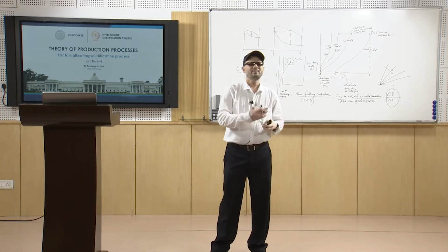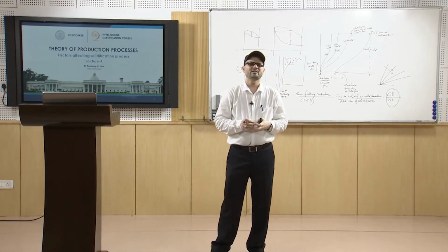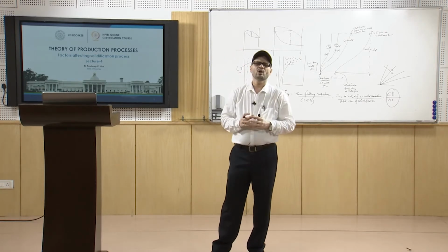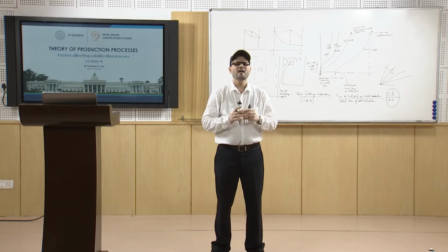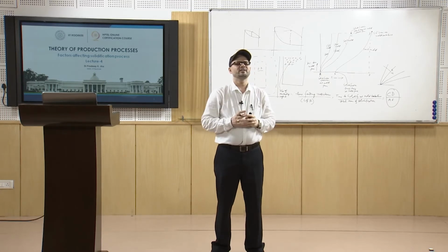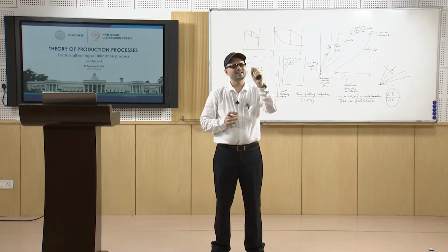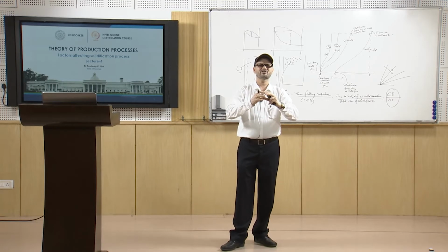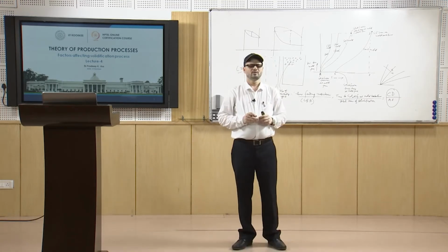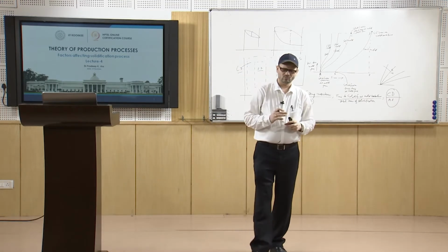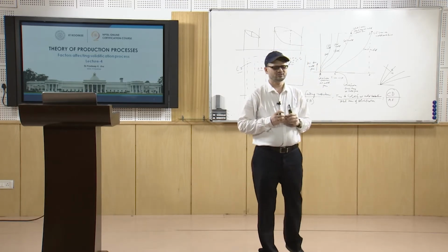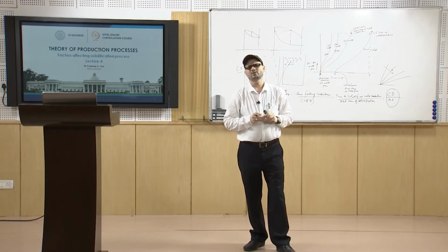So, you have many ferrous materials, a variety of steel, or duplex steel, which basically use these nucleating agents to refine the structure and make the grains refined. Now, we try to have these equiaxed type of structures, and because the columnar